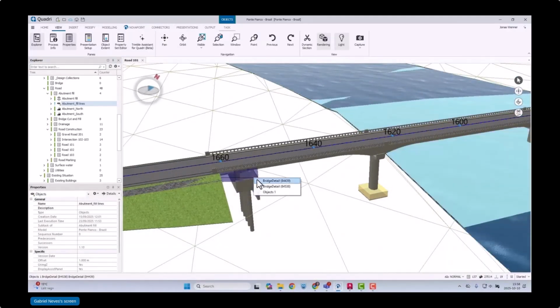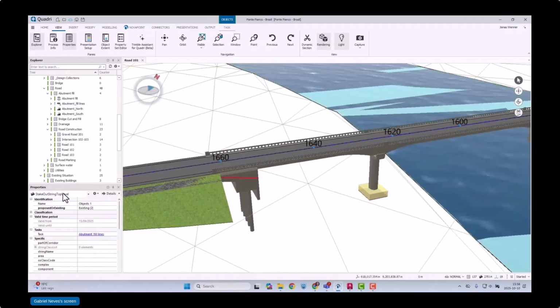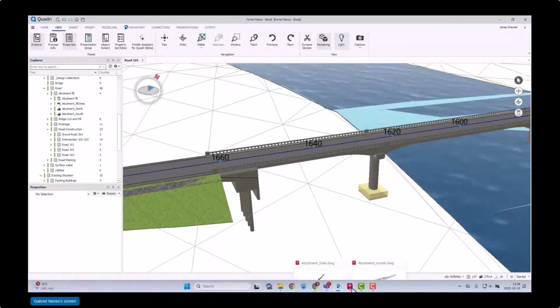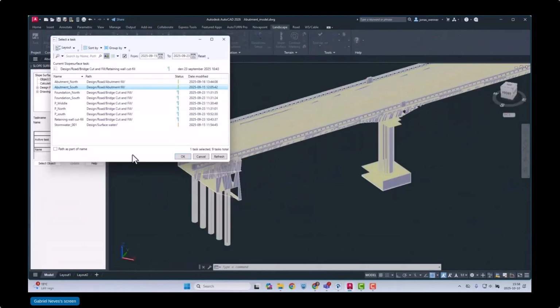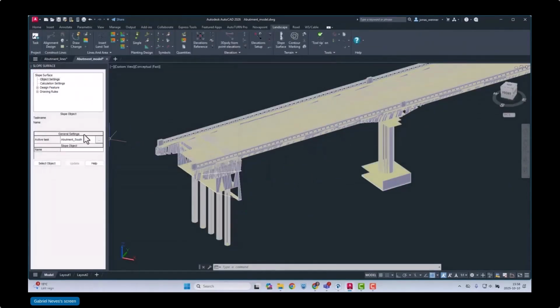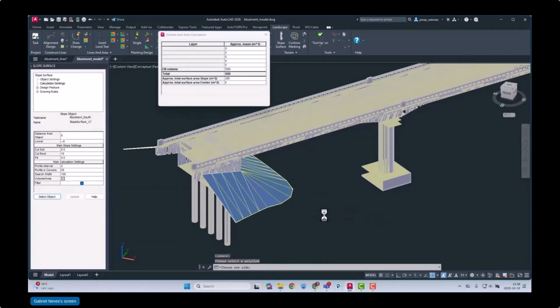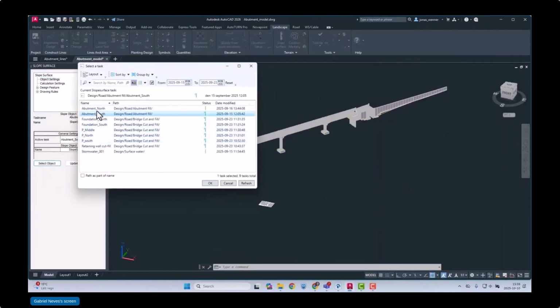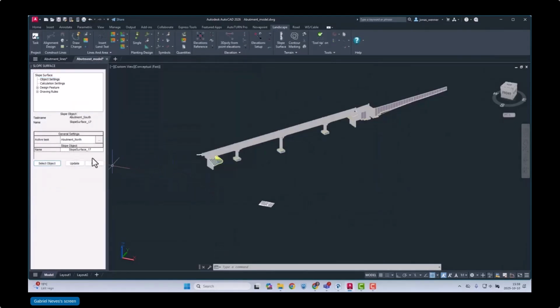Right. And then the next example is modeling those embankments, as we call them. What we do here is directly in Quadri, or of course extracted in some way from the bridge designer, I can just extract some 3D lines from the bridge, and then bring them into my CAD platform where I have functionality connected to NovaPoint. In this case, we just create these embankments at the end of the bridge, and this will also have an automatic volume calculation. How much fill is it here?